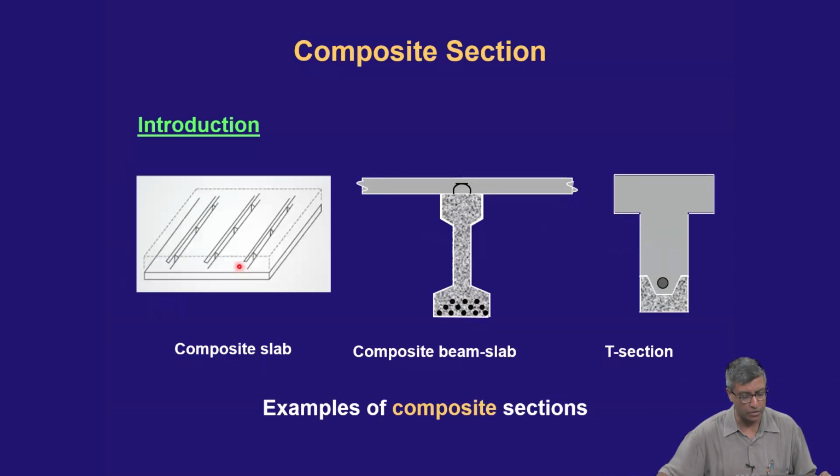What we saw on the field was that they will have a precast base element, sometimes they call it a filigree element. Over that, there are certain lattice girders to have the composite action, and it also helps to lift it. And then they will be placing the concrete here. This next one is very common both in buildings and bridges, that you have a precast beam, and then you can have a cast in place slab. Okay, you can also have a precast slab. Okay, but then that's not composite. Okay, here this is the composite.